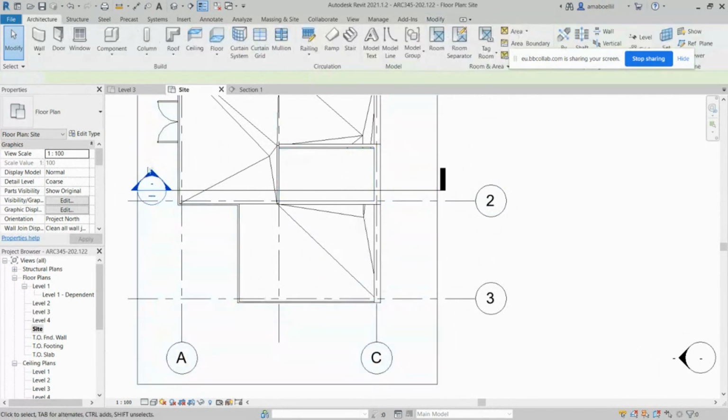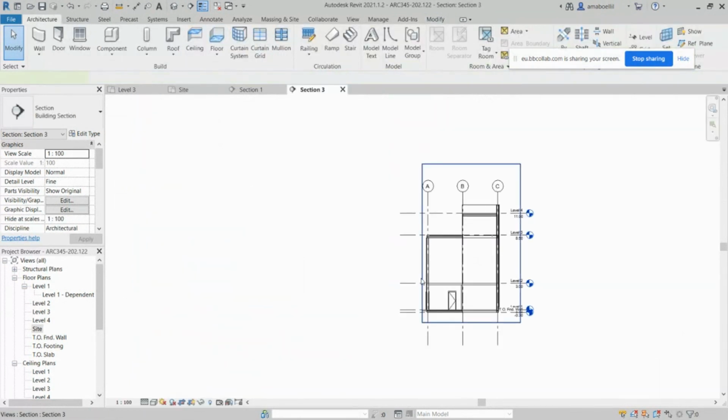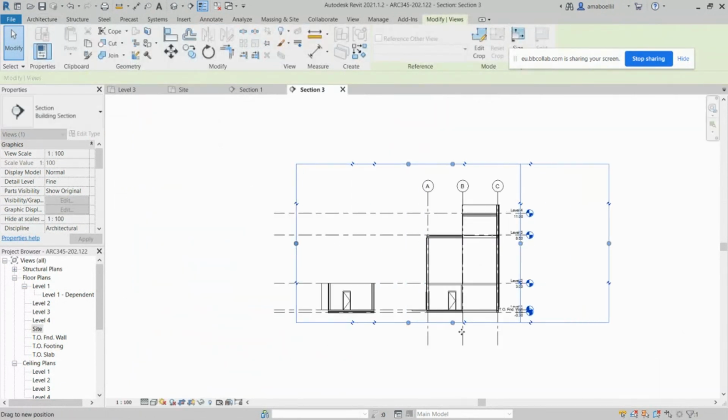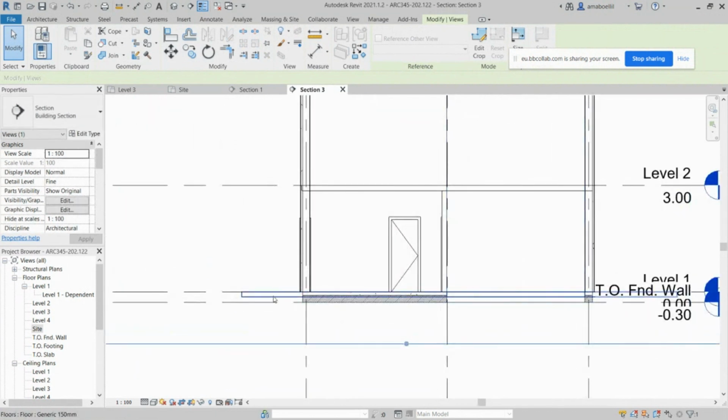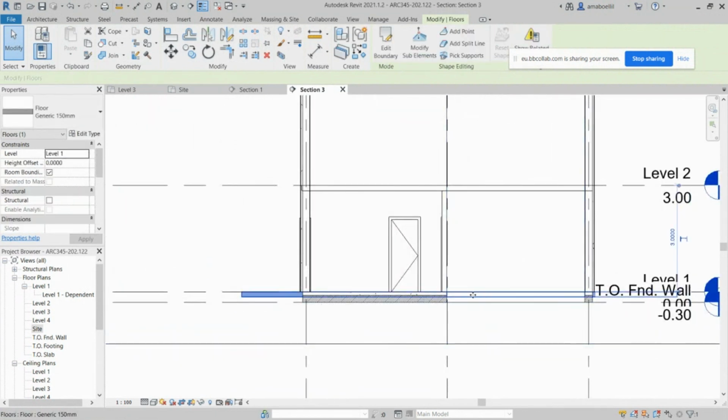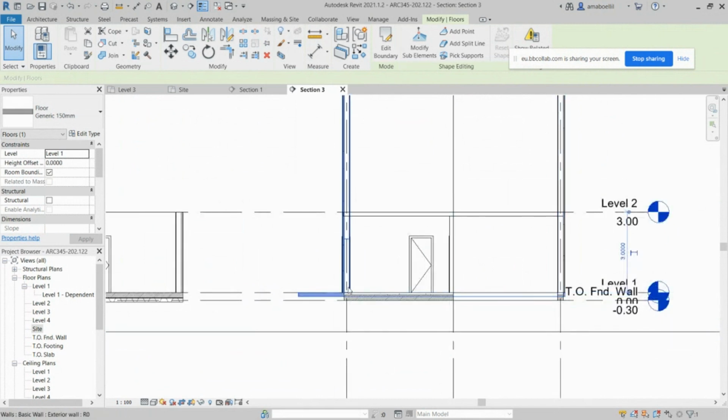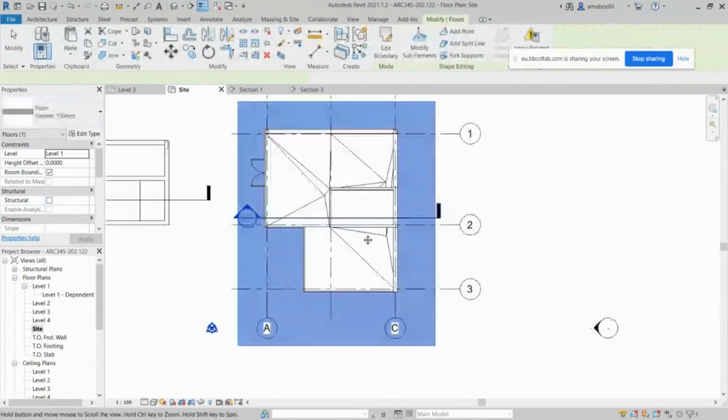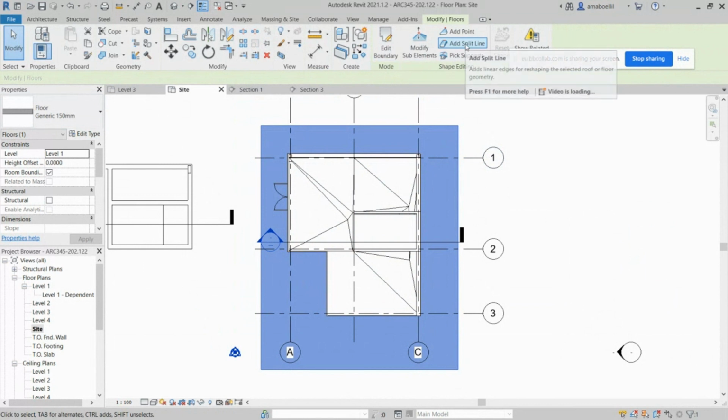If you build this, you would see that the floor is overlapping with the other floor, so you had better arrange it so that you go a little bit down compared to the floor that you have, because we already built the floor inside the building, and we build another floor. As you can see from here, they are overlapping, so it gives you a warning. If you want to keep the same levels, what you can do is make a cavity in the building. You come to the premises of the building and make a hole in it like this, pick that and edit it, so that you add a set point with the boundary.